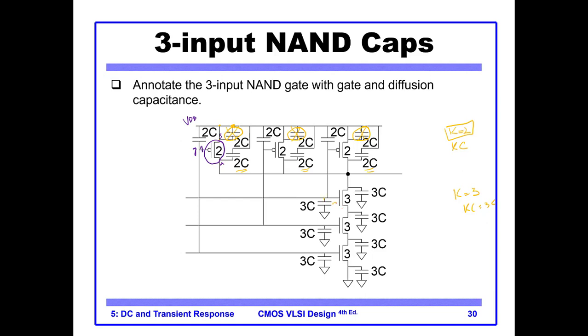Look at the case of NMOS. At every gate, so this is the gate terminal, we have a capacitance of 3C. Similarly at the drain we have a capacitance of 3C. But note that this terminal is common. Remember the layout: whenever there were three NMOS in series, they share the diffusion regions. If you remember, for example, this was our N region, and we have the poly lines here.